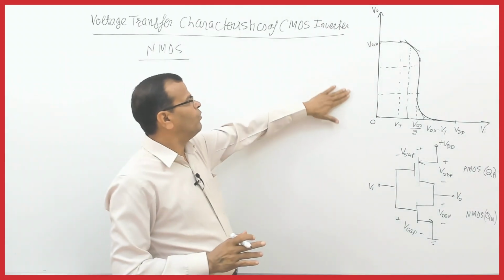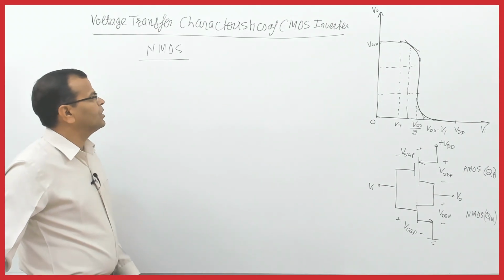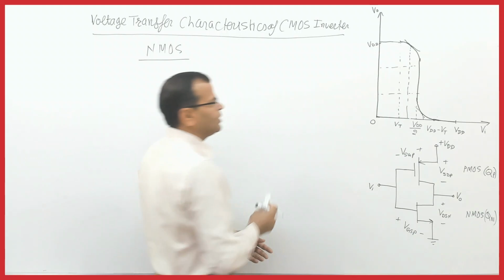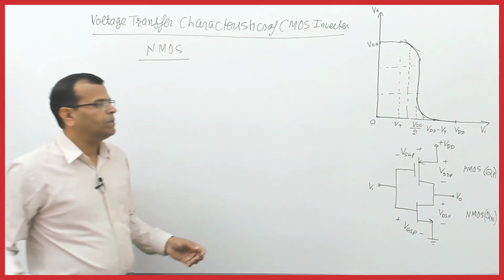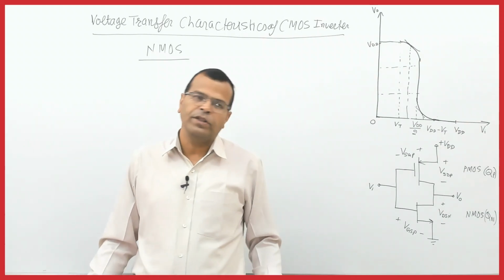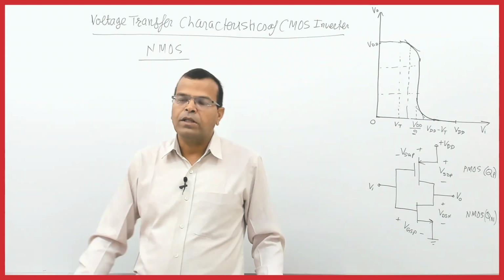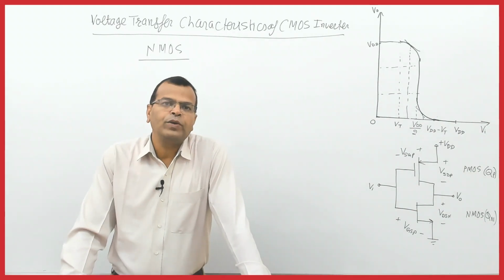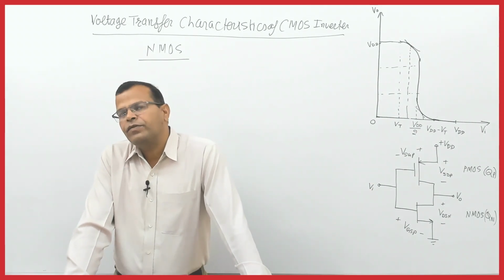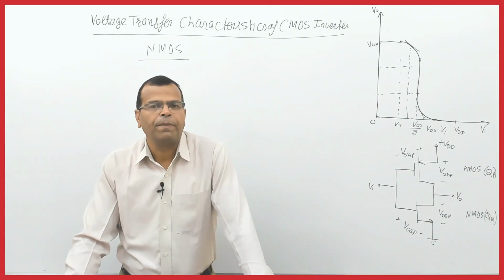Fine. So when we talk about NMOS, we will see its operation in both ohmic and saturation region of operation. Similarly, PMOS, although it is operated in cutoff and ohmic region for switching operation, will always pass through the saturation region of operation when it changes its state from ohmic to cutoff or cutoff to ohmic region.